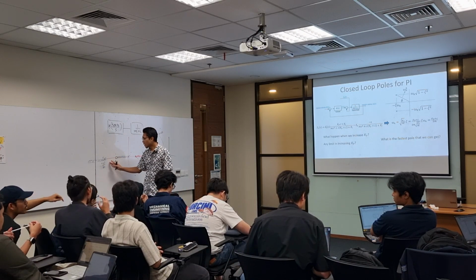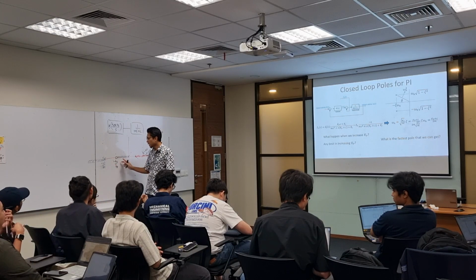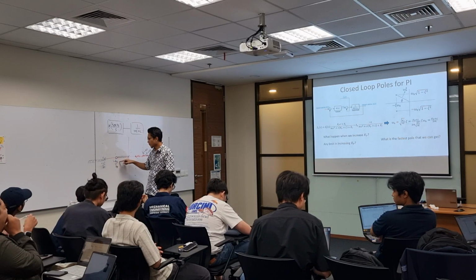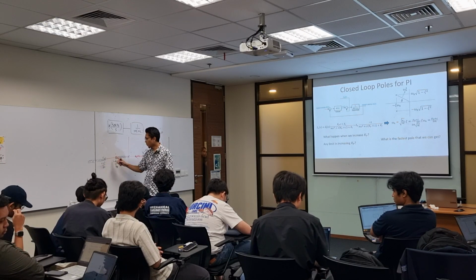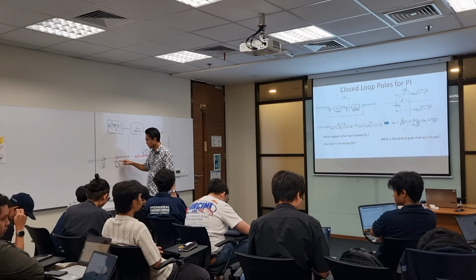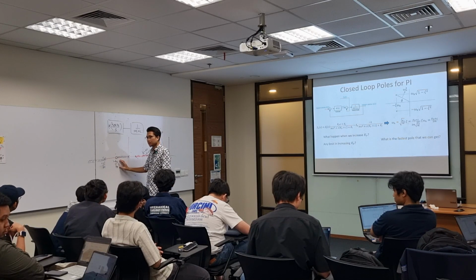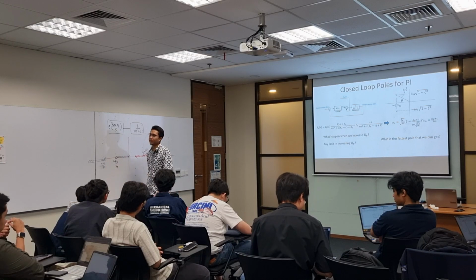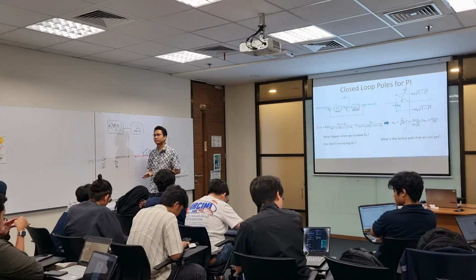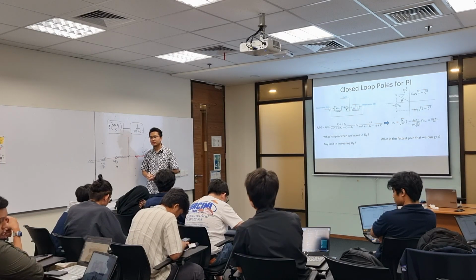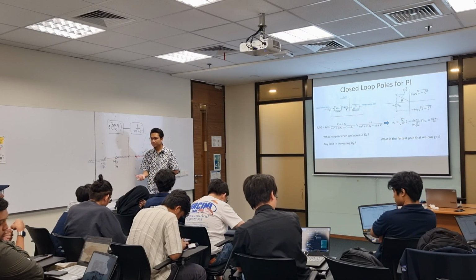Yeah, the left one, if we assume the zero to be in between the open loop poles, because we can adjust minus K over Kp. If it is there, then the system will always be overdamped. It cannot be critically damped, cannot be underdamped. You understand what I mean?